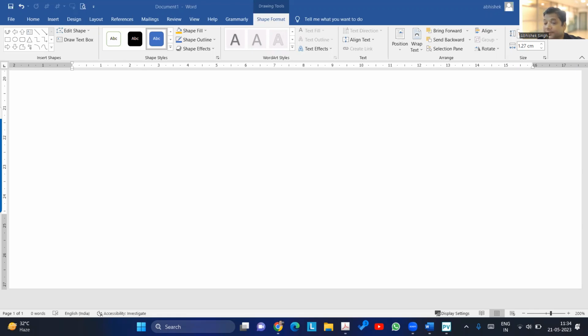Up to minus 45, 46, we can use the MDMT exemptions, do the calculation, and satisfy even without doing impact testing. But if any doubt is there, we can always do the impact testing and make sure whether it is ductile or brittle. Below minus 48, definitely you have to do impact testing.